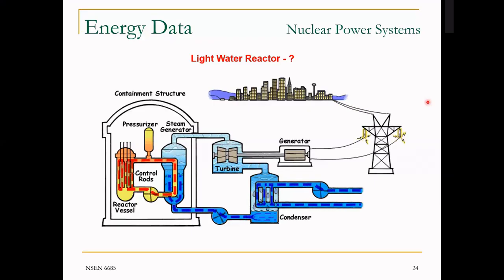And it's obvious from the name, in the boiling water reactor, we allow liquid to boil in the primary loop. We actually take cold liquid here, it goes into the reactor vessel, boils, and we take the steam up here. So we don't have that connection here. That's in the boiling water reactor. In the pressurized water reactor, we cannot allow water to boil inside the reactor core for many reasons, and we're going to touch base on that later in the course. But we use a component called a pressurizer. That's to increase the pressure of the primary loop, so it doesn't allow water to boil in that primary loop.